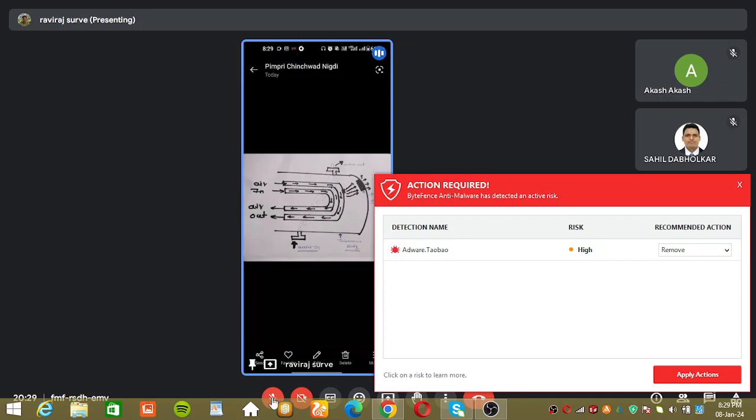So that's the reason we use the bursting disc in the intercooler or aftercooler body, which bursts at the set pressure or the limited pressure. It saves the intercooler and aftercooler body from damage. So this is the function of the bursting disc.